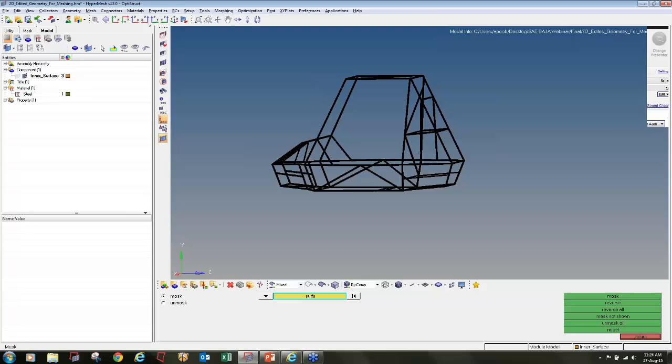So that's why the forces I am going to select here are absolutely wrong. Similarly with this roll cage, please don't try to make a similar roll cage. This roll cage is extremely heavy and it will not sustain any loading condition. It will fail the moment even a bird sits on it.